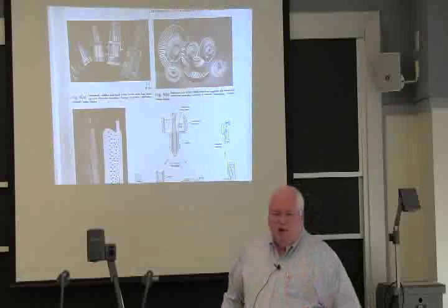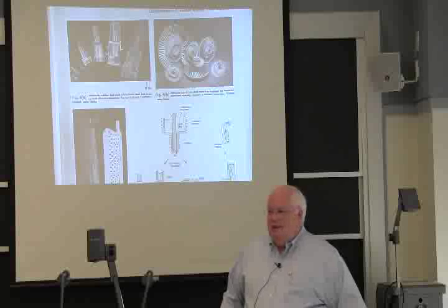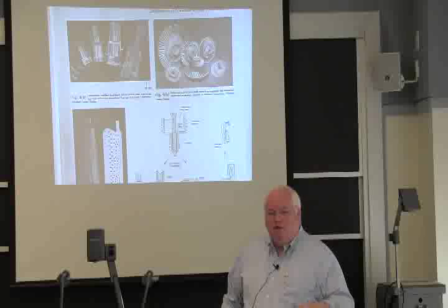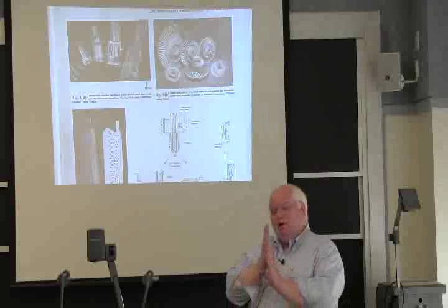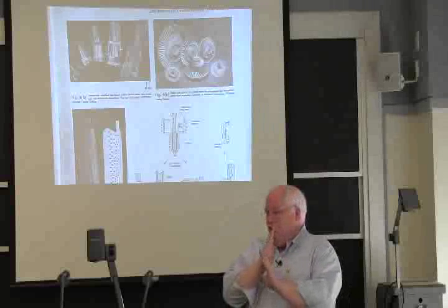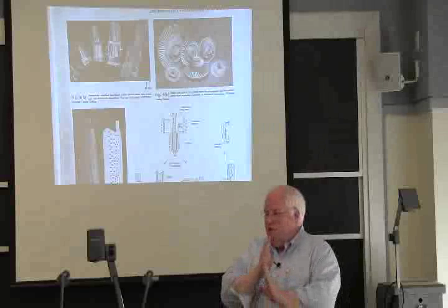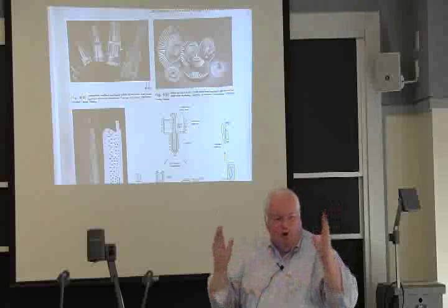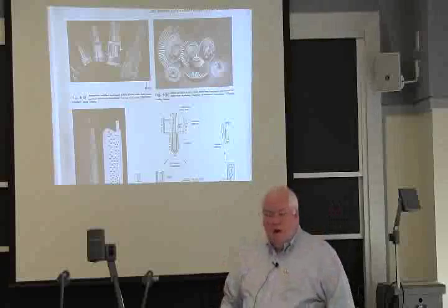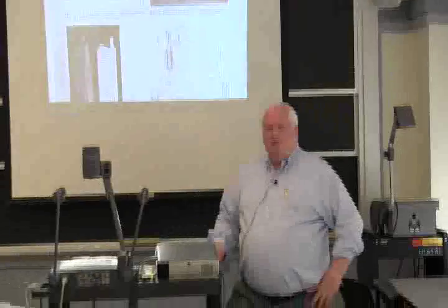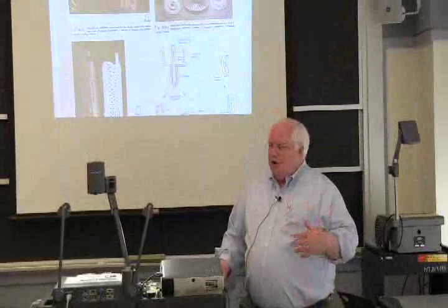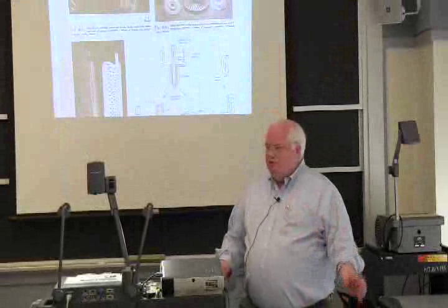Today, the walls are getting down as thin as 15 thousandths of an inch. Really, really thin walls. The problem with going thinner is if you have a little bit of core shift, you've got a ceramic core in the middle of that thing when you're growing it, and you get a little core shift of 5 or 10 thousandths, and you've got no wall left. So the way they inspect those right now is they basically put them in a CAT scan machine. And for $500,000, you can buy a CAT scan machine for metals.